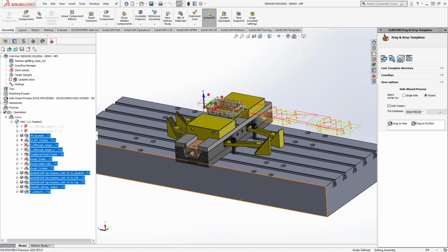Okay, looks like that's exactly what I was looking for. Okay, okay. So there is a way to transform, copy, repeat your toolpaths in many different ways. It just depends on your setup. If they're all equidistant, I just literally got off the phone in a training session where the customer had a base plate where he actually set up the positions of each of his individual parts, so he knows for sure that they will be 10 inches apart. In that case, you can use Translate. You set up one offset and you just say that it's 10 inches apart.